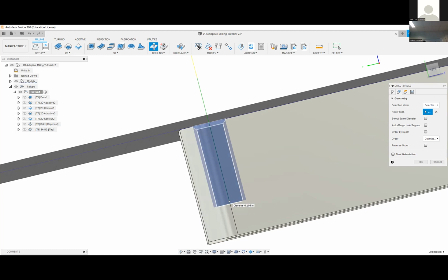On a tap, you're cutting threads and you're making chips. If you go to the bottom of even a pointy hole, for instance, you're going to mash some chips into the bottom and you're going to jam the tap and it's going to break. So we're going to leave like 10 thousandths of an inch, 15 thousandths of an inch of space, so that we don't have to worry about breaking the tap.